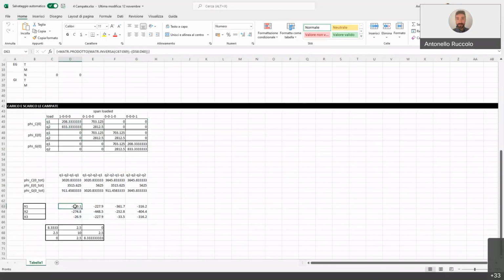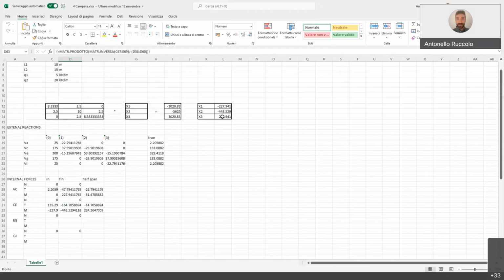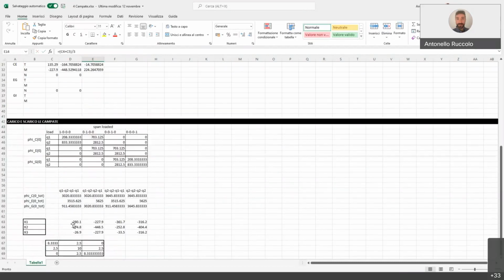So we can just reuse the equation that we adopted in order to find the static unknowns, which holds for the flexibility coefficients and the known vector. We use the same formula and the same matrix here, but calling every time for a different vector associated to a different load condition of the structure.